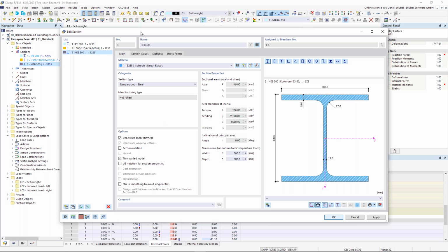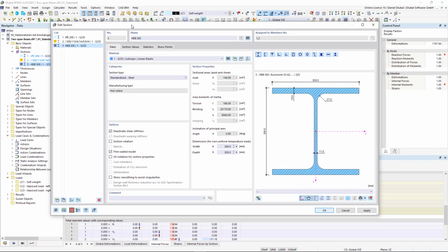And this can also be considered for your hand calculations. Because when you calculate by hand, with the help of some tables in your books, then it is kind of rigid. Then the books take no shear stiffness into account. Yeah, but in reality, there is a little bit of shear stiffness, especially when you have solid cross sections or timber cross sections. However, it is recommended to consider the shear stiffness for the deformation analysis.